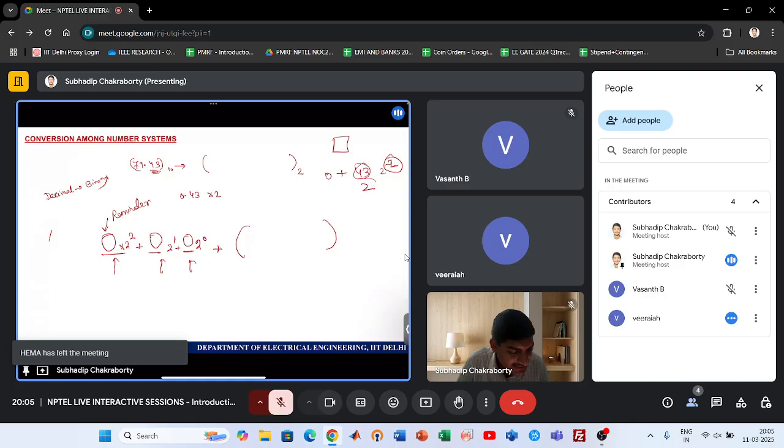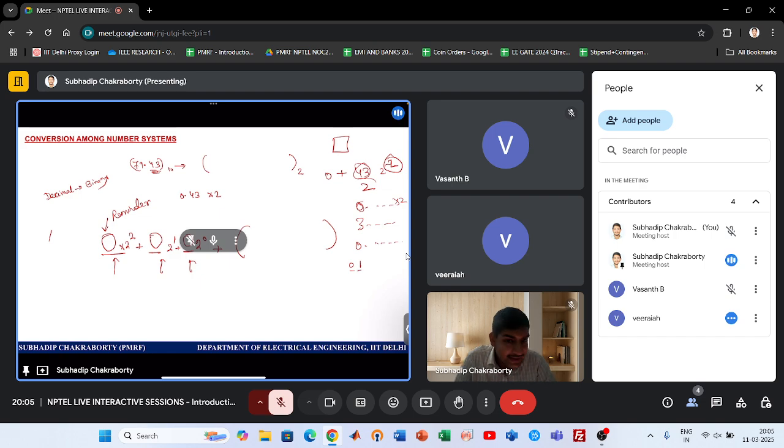You see, for a fraction multiplied by 2, the whole number part is either 0 or 1. It cannot exceed 0 or 1. It cannot be 3 point something because we started with 0 point something. We can at max be 1 or 0. But we multiplied by 2, so we need to reduce in the next stage. So we went to the next lower order in the fractional sense. So that's why 2 to the power minus something. Because we multiplied, we need to reduce to get back the same number, but encoding it with 0 or 1.